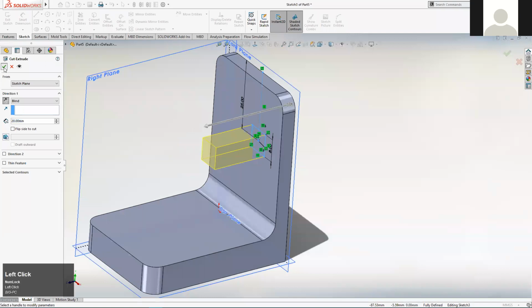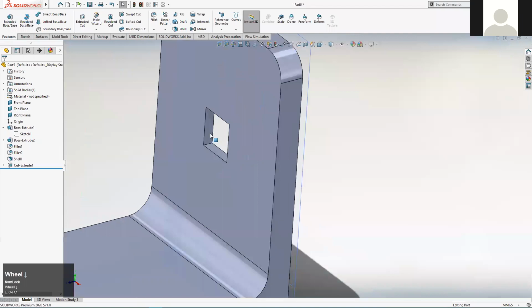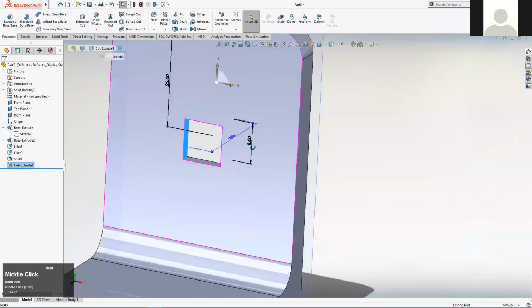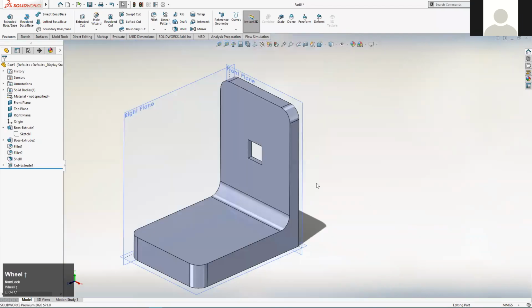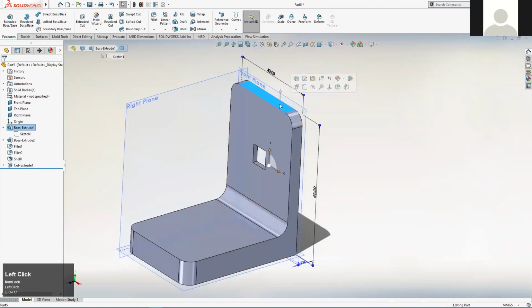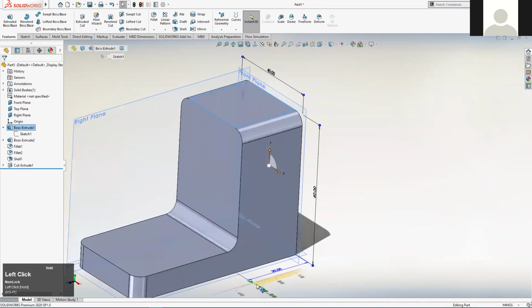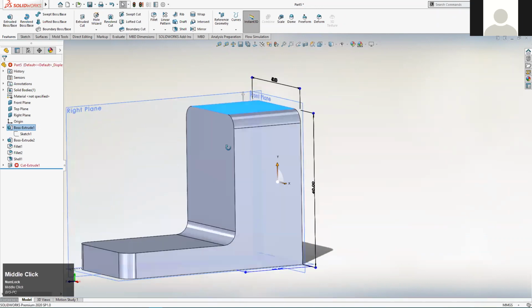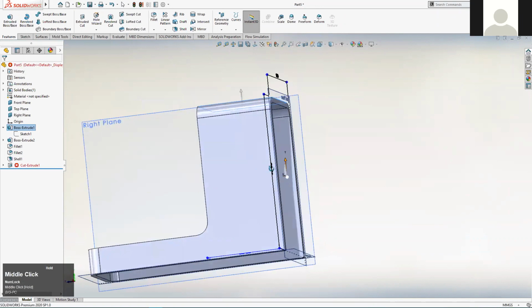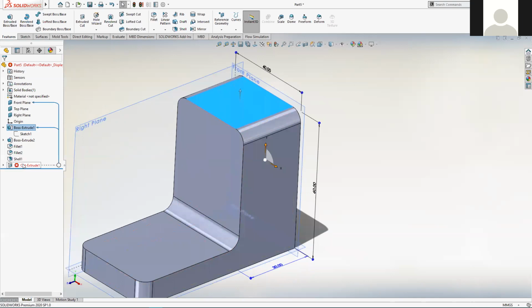And then we okayed that feature. And it would achieve what we needed it to achieve. So it's cut all the way through. So we're happy. But then someone in our design department says the L brackets that we produce, we've made a decision that this 5 mil wall needs to be much, much thicker for the purposes that we need them. So let's bump this 5 mil wall up to 30 mil. And then lo and behold, our cut doesn't work anymore. So you can see it's less adaptable to change.